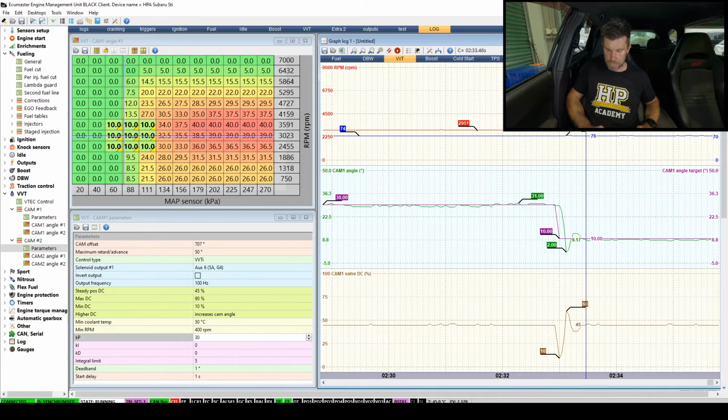We can also see the cause of that oscillation is the reversal of our duty cycle there. This is an indication we've probably gone a little bit far with our proportional gain, but we can drag some of this back by using a derivative for our braking effect. So all's not quite lost just yet.